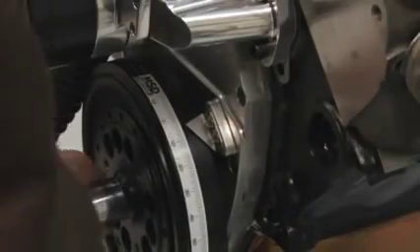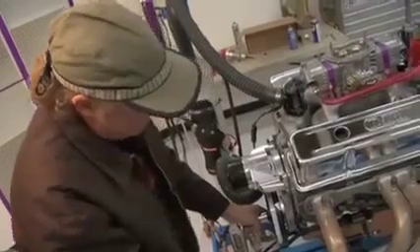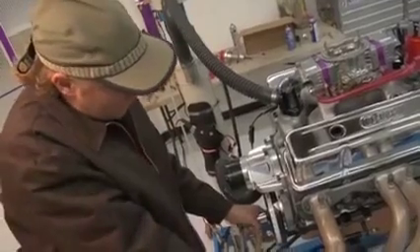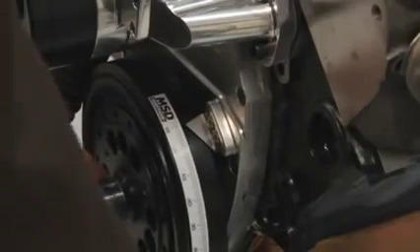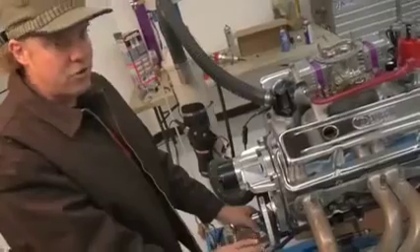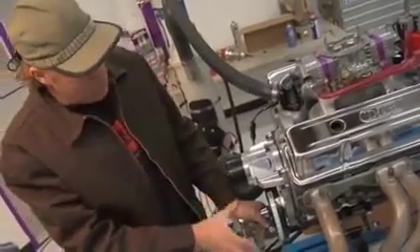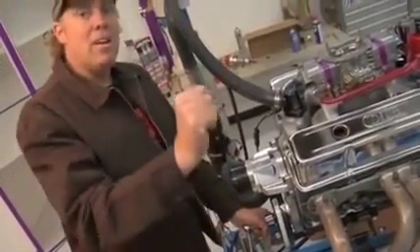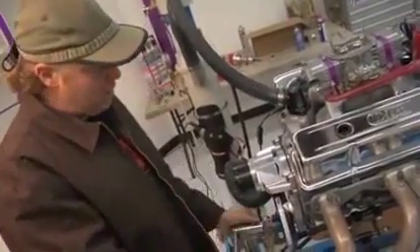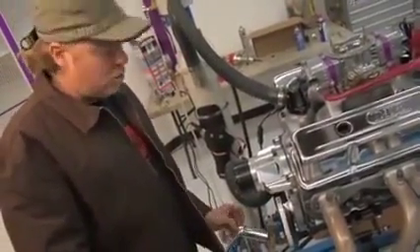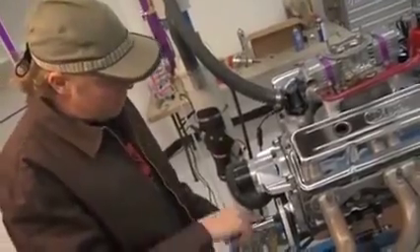There's 10 degrees before, 5 degrees before, and then I went a little bit after, but that's roughly 0, or right at top dead center. Now the piston is moving back down the hole, and now it is 10 degrees after top dead center. So as the engine rotates, the piston comes up, stops for just a millisecond at top dead center, and starts to move its way back down. Now that's the mark that we use to determine ignition timing.